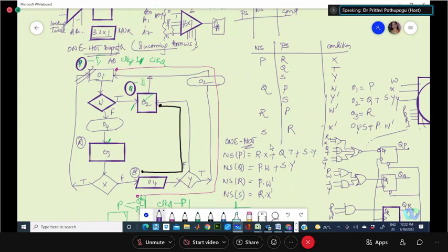As I'm saying, this will be based on the discretion of the designer. We are saying how many states your design has, what is the complexity you are handling, how many states you can easily access or maintain. In your mux method, the number of flip-flops is less because you are taking powers of 2. The 2 powers of the number of flip-flops you take will address that number of states.